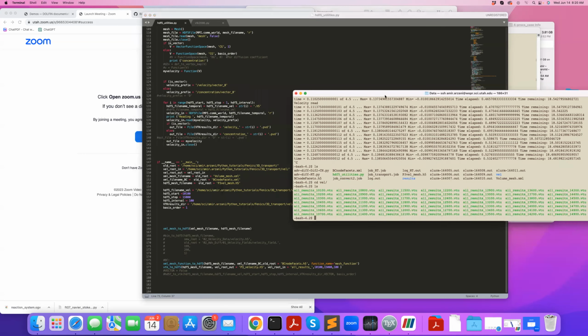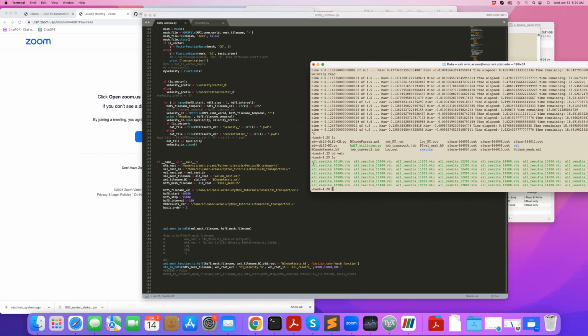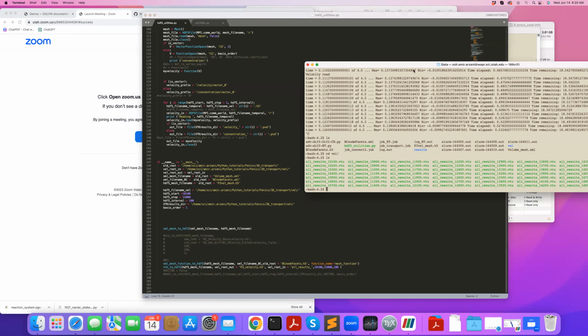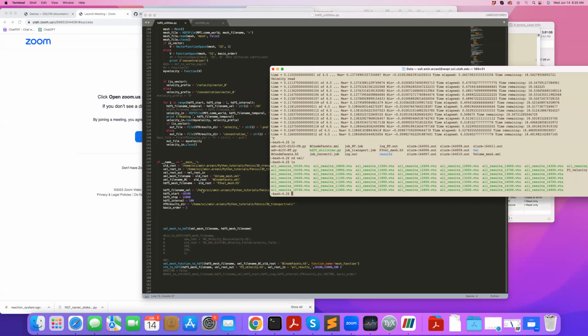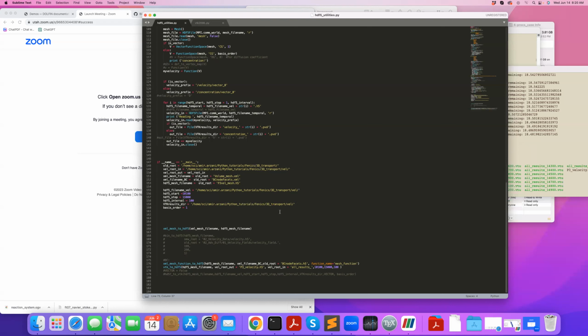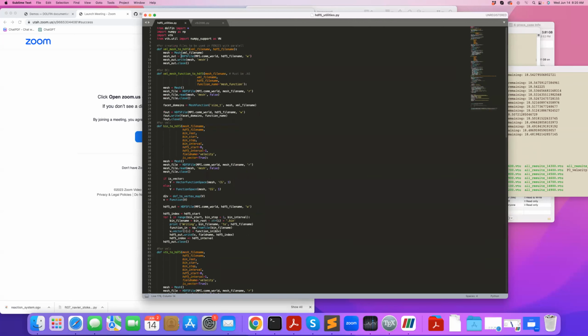In my case, I have my velocities from Semascular called all underscore results, and then the different values. You can see all the files here, and these are what I'm defining here to read. And then where I save my files, the velocity file. So there are 3 functions here that will run when you run this code. The first function converts your XML mesh to an H5 mesh, and the second one does the same thing for the boundary condition tags. Nothing fancy, pretty simple. It reads the XML file, converts it to H5.